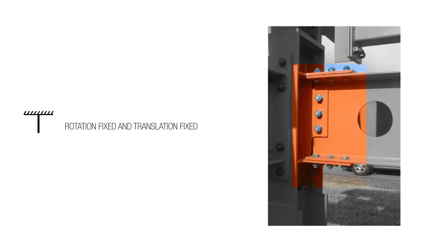So this is a moment connection. We saw this before when we talked about steel. You know it's a moment connection because we've engaged the flange and the web, and we're holding both of them in place. And so that would be a rotation fixed and translation fixed. It's not going to slide up and down. It's not going to rotate.